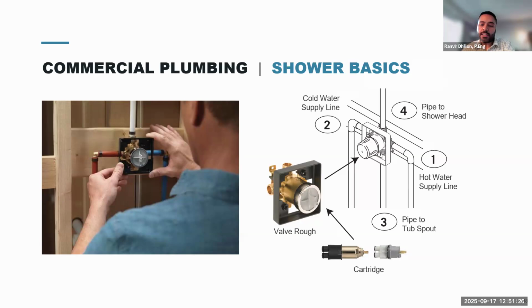One thing to note is valve roughs, cartridges, and trims typically are not interchangeable between manufacturers. So if you have one manufacturer's rough-in, typically you won't be able to install a different manufacturer's cartridge or trim.